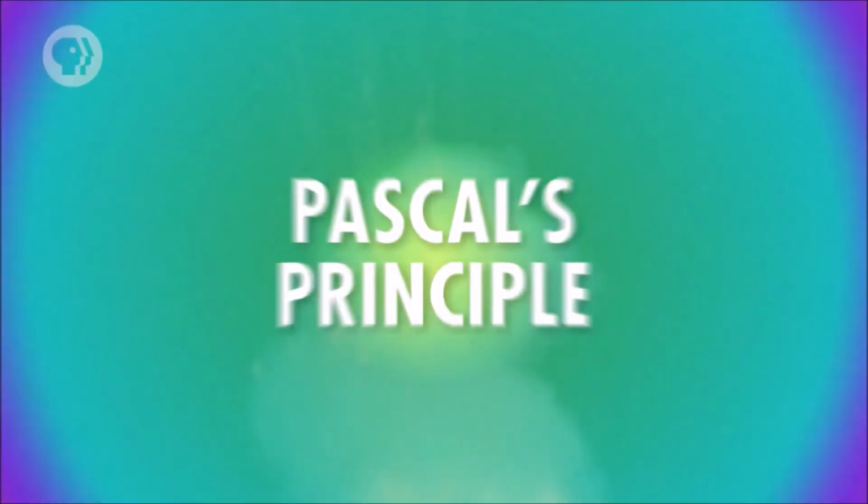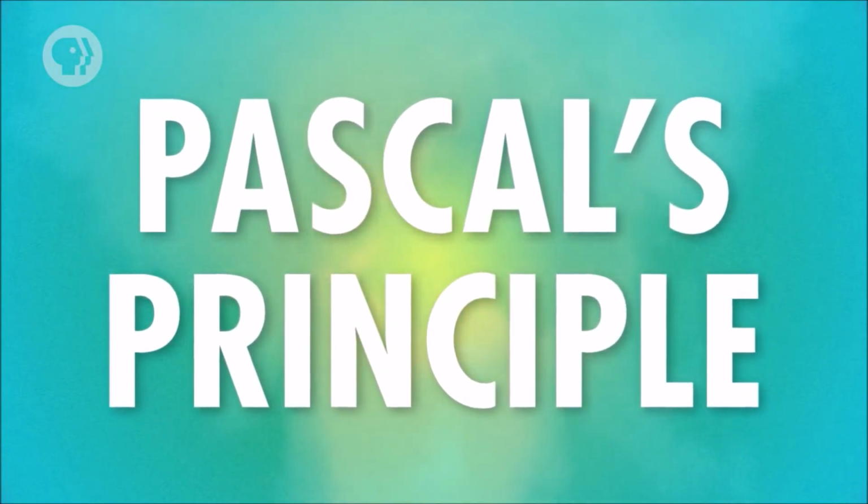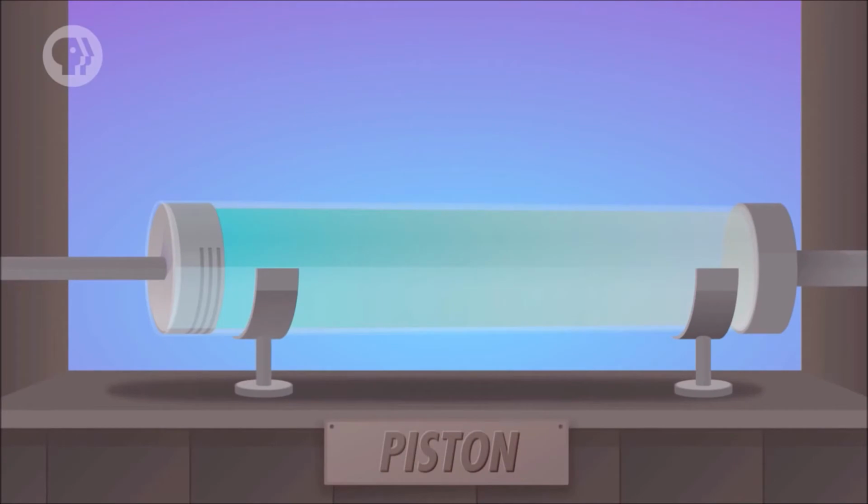Today, that concept is known as Pascal's principle, and it's the reason hydraulics are so useful. Say you have some water in a tube with pistons on either side. Pascal's principle tells you that if you use the piston on the left side to apply pressure to the water, it will exert the same pressure on the piston on the right side of the tube. And the pressure is equal to the force divided by the area.